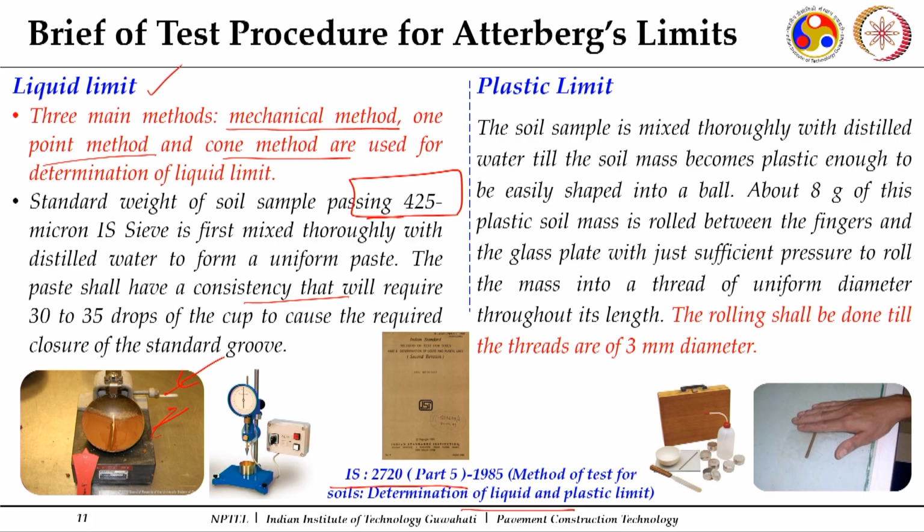add some more water, then again cut the groove and check again. This is how it is repeated, and finally you look for the one where it gets closed down at around 25 blows. So this plot is plotted between these drops and your water content.